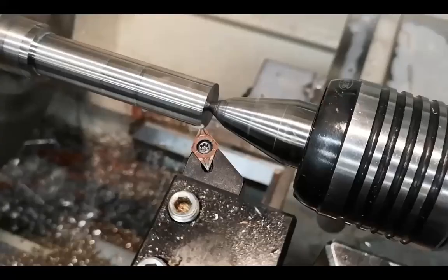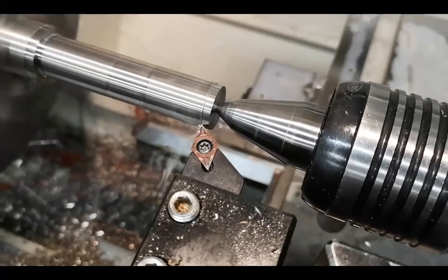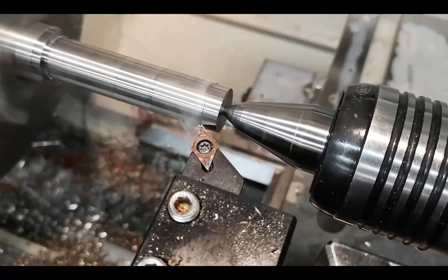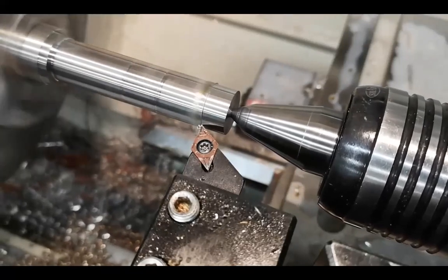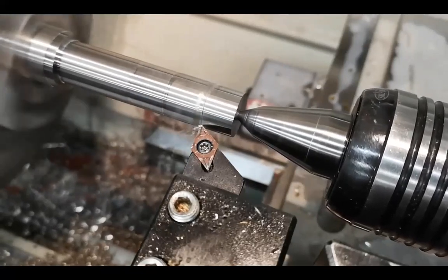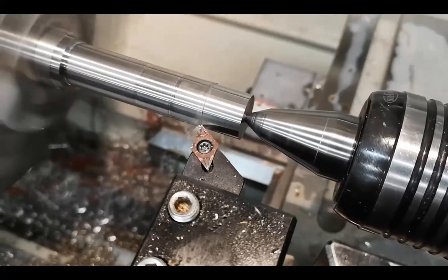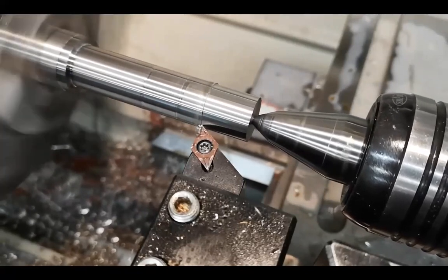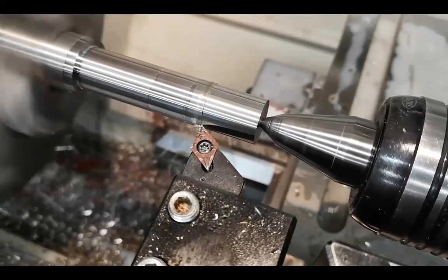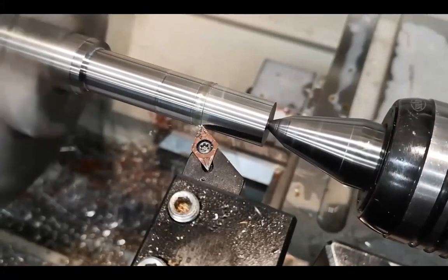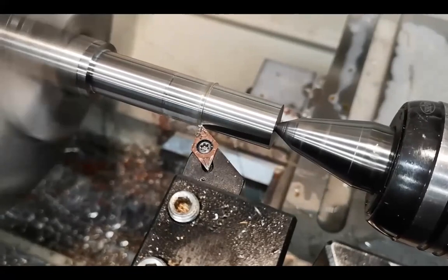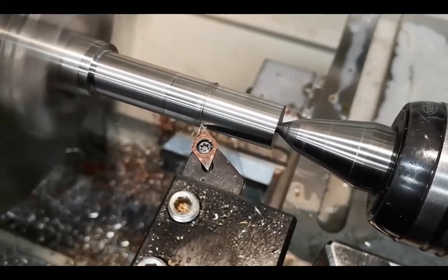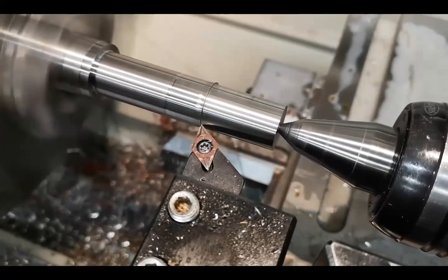So starting off, any dimension in existence has some tolerance to it. The tolerance specifies how much higher or lower a dimension can be from nominal and still be acceptable. The space between the upper and lower limit is often called the tolerance zone. Think about it like football uprights. Each upright represents a limit, upper or lower. To score a field goal, we kick the ball towards the center, but no matter how the ball flies, as long as it ends up between the uprights, it's acceptable, and our parents will still love us.